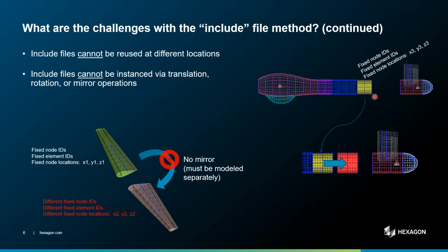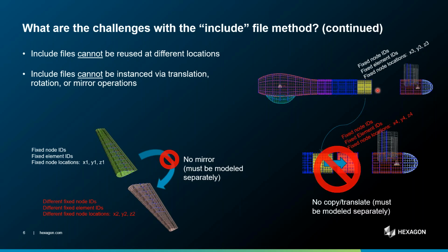Similarly, if I want to make the fuselage larger, if I want to extend it, perhaps there's a region of the fuselage that I would simply like to translate and instance. Once again, I can do that with the preprocessor, but the preprocessor is not an obstacle, but it is a hurdle. It's going to be extra work. It would be nice if it was an instance of the portion that I'm actually going to use. That way, a change to the parent, I'll call it a parent, would automatically mean a change in the child as well.